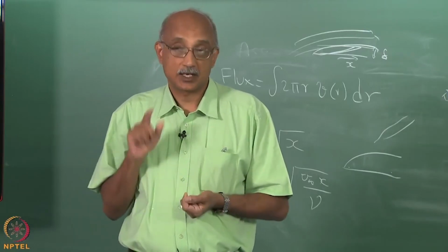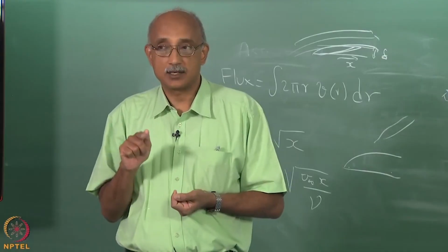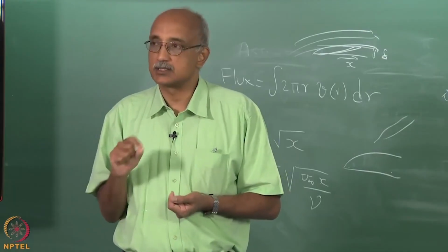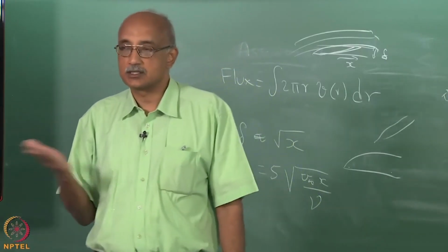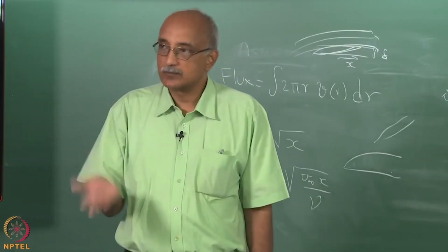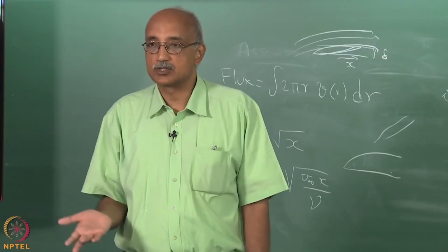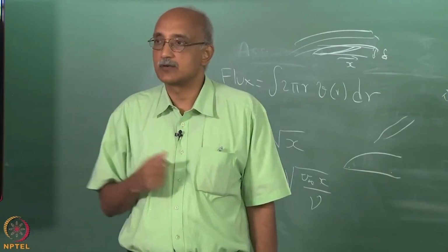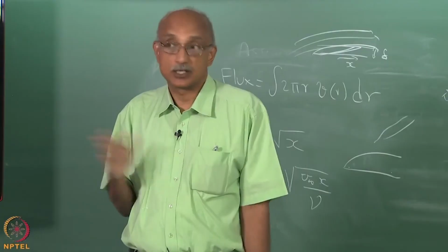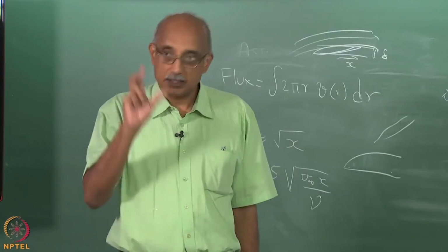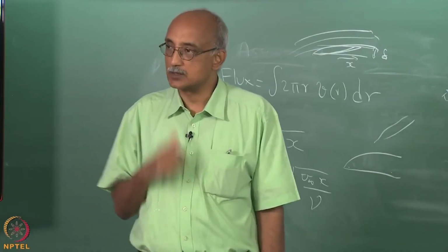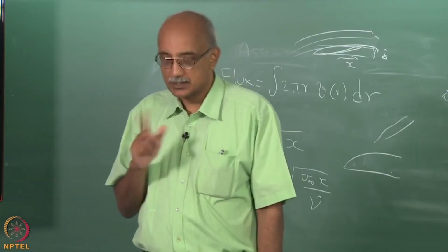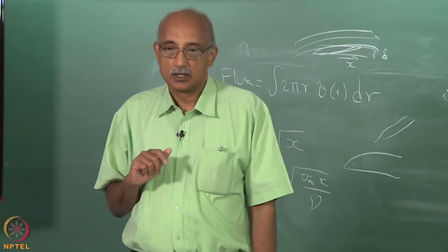The flux of elemental silicon, not every species containing silicon. So, if the silicon element is contained in 50 species inside the CVD reactor, 25 of them could have a flux towards the substrate, 25 of them could have a flux away from the substrate. That is okay as long as the net flux, when you add up the contributions of all the species, is towards the substrate. That is a self consistency check.